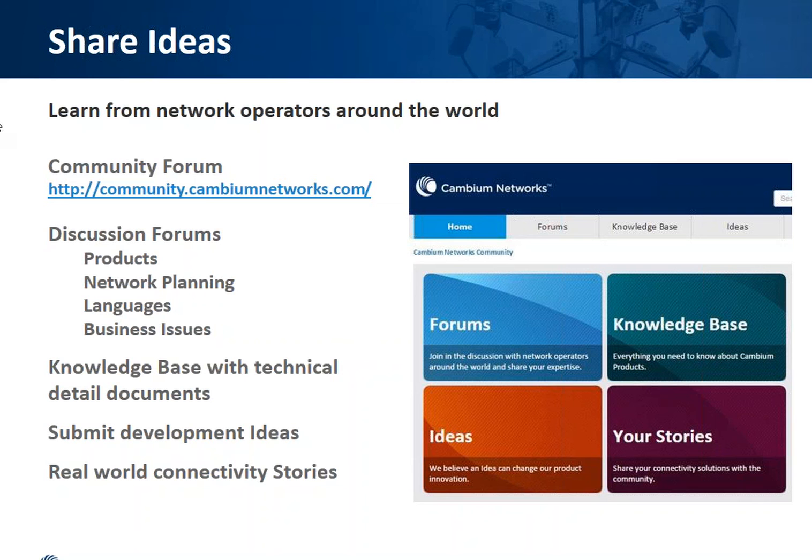You're welcome. Matt, the next one is about total throughput. What's the total throughput available for a 5 megahertz and a 7 megahertz channel? And I know it's going to get right back to physics. Yeah, absolutely. Depending on the modulation level that you can achieve up to the maximum throughput per channel size. And this is the same across all the 450 product platform. In a 20 meg channel, you can do upwards of 100 megs, typically around 130 or so.